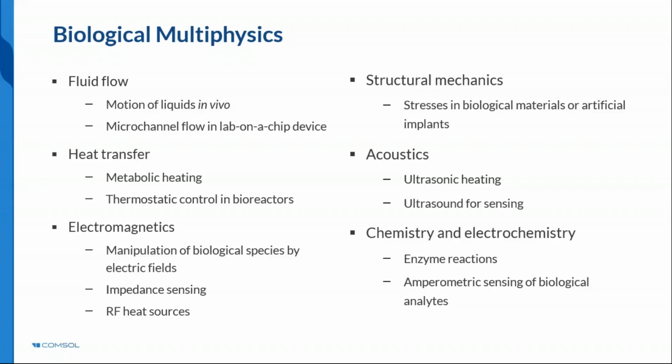The advantage of the multiphysics approach is that it allows the inclusion of many different equations and types of physics to be amalgamated together in a single model with a common user interface. The approach is a real advantage in biosensors where multiple physics are combined into one device. For instance, fluid flow physics is an important element in lab-on-chip devices. Accurate electromagnetic modeling is important in simulating impedance sensing or in the modeling of biological separation processes within electric fields, for example, electrophoresis.